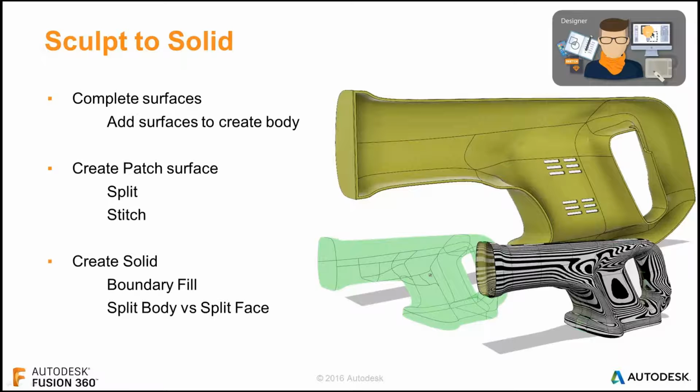What we're going to do now is start transitioning into, for the next hour or so, this free-form body. We will complete the free-form body and then move into the solid world, so we can take advantage of the traditional solid modeling tools to augment the design. We will be adding more surfaces or T-spline bodies, again bringing things together. We will also look at a couple of new tools and a couple of new approaches versus drawing the basic primitives. Then we'll create a solid model from all of these faces and surfaces.